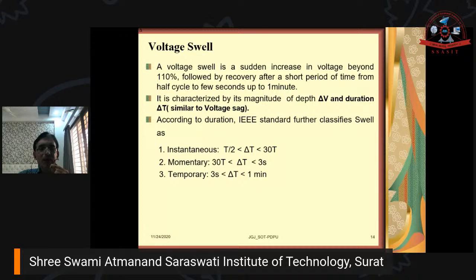Generally we write the round figure 440 volt, you might have seen on the distribution boxes, 440 volt danger. But actually, we are using the distribution transformer of voltage ratio 11 kV by 0.433 kV. So what is the maximum secondary terminal voltage? 433 volt. And after that there would be a drop in the cables, in the distribution boxes, in the wires, and therefore the declared nominal voltage in India is 400 volt.